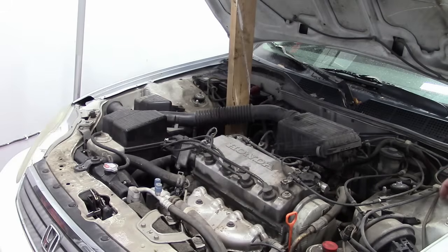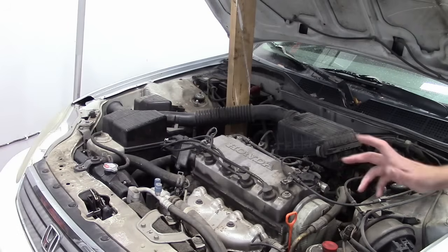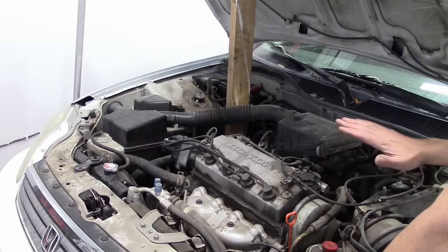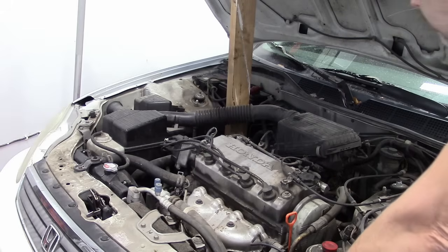All right, I am sure you guys will agree with me that this car has a compression problem, but it is not the cause for the no start, for sure. But again, listening to that dip in one of the cylinders, you can hear that there's not that steady, even beat with the cylinders. One of them sounds different, and that almost certainly is because of compression loss, and it's the starter motor having an easier time going through that cylinder, less resistance, so it changes that sound. That is not the reason this car won't start, though.